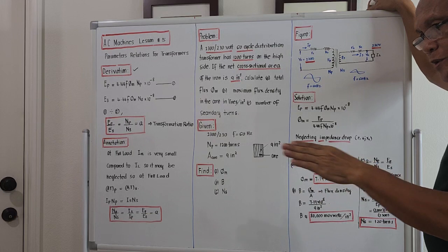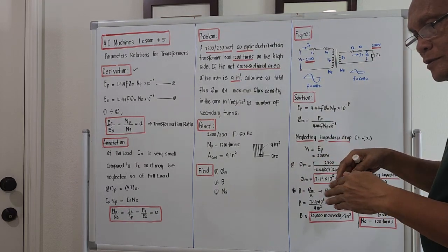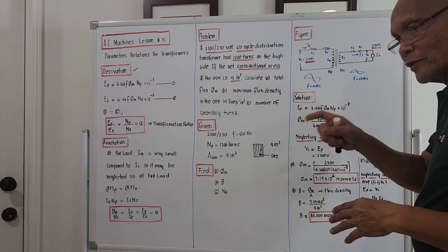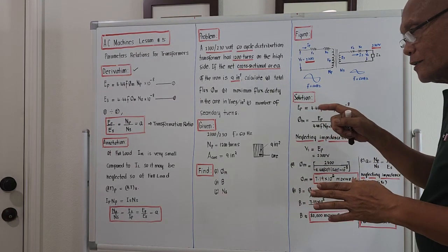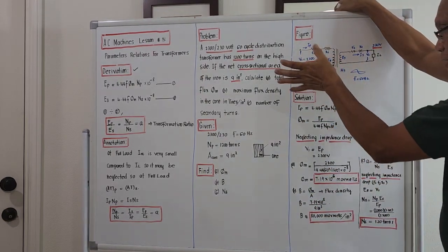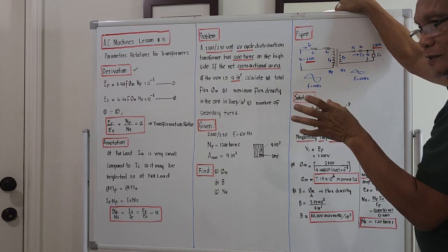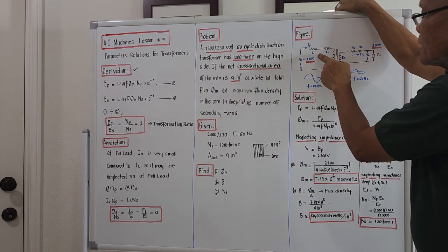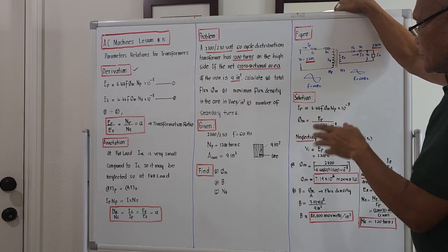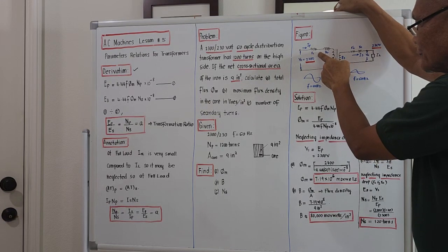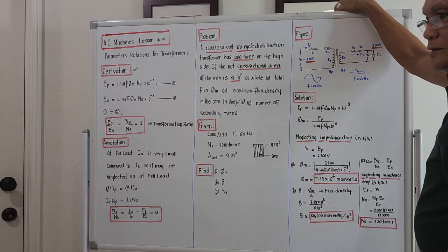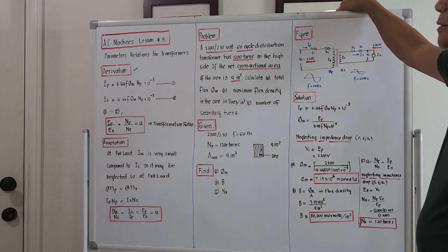the number 1 component of a transformer is actually a winding, right? So for a winding, whether we like it or not, there should be a very, very small resistance, okay? And there should also be a so-called inductance. So actually, if we bring out the equivalent of that impedance drop, it will be R1 and X1. There is no such thing as a perfect transformer in which the internal resistance is 0 and the inductive reactance is 0. There is no such thing as a perfect inductive coil. Okay?